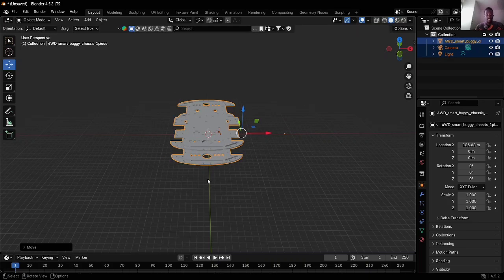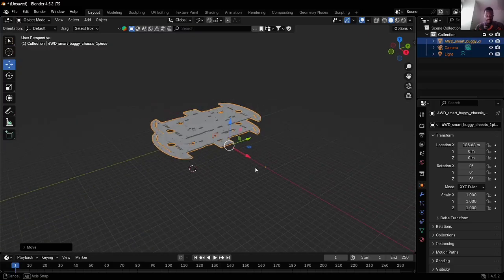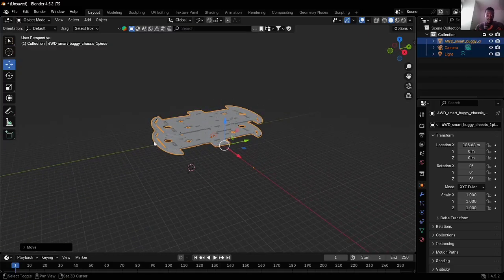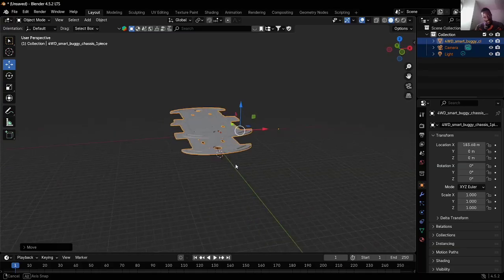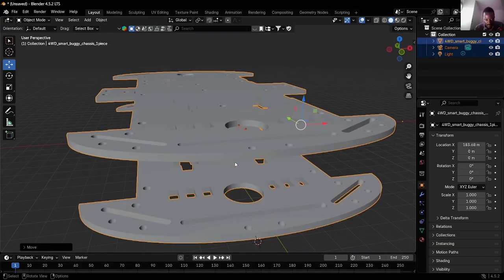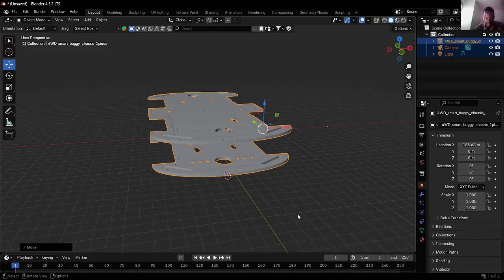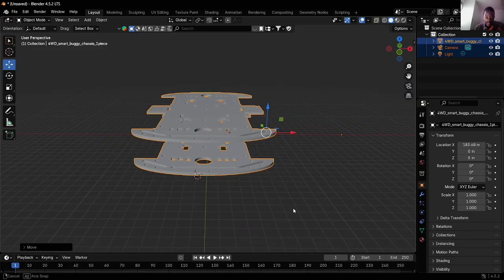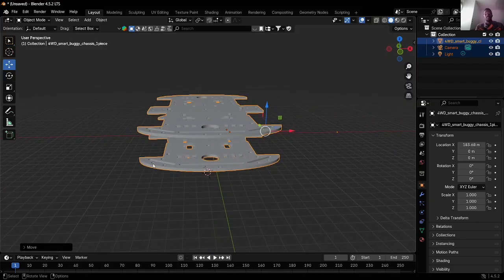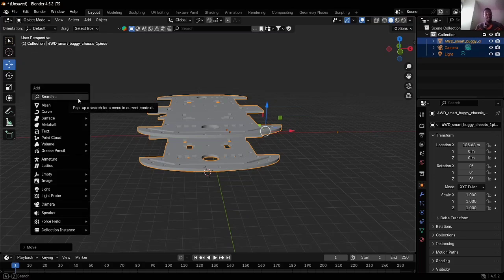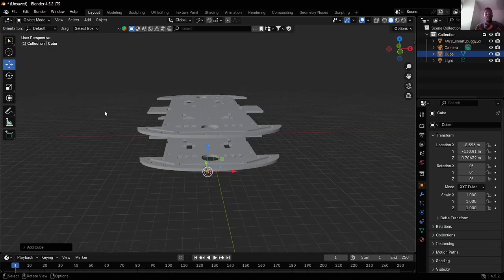I want to put that marker, this one, directly on the front. I put it here. I hope it's not inside. And yeah, somewhere there. I'm now designing that part, and I'll just be using a cube. So I'll press Shift A and add a mesh cube.